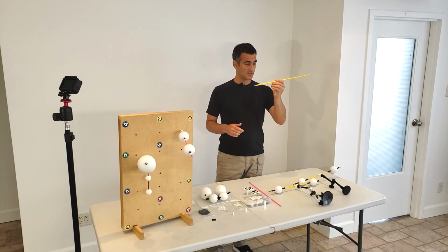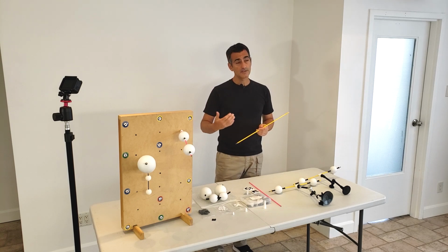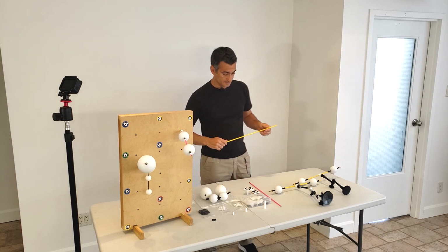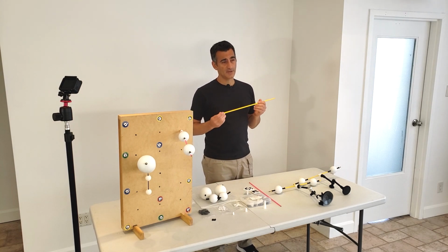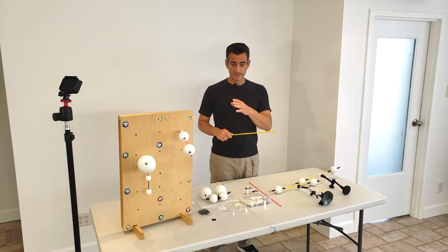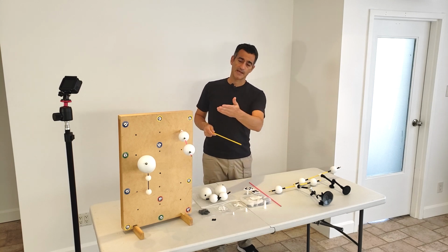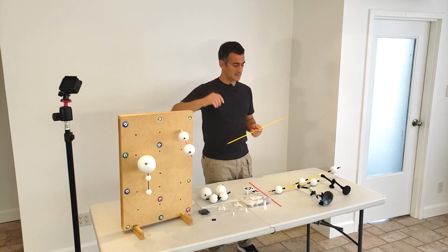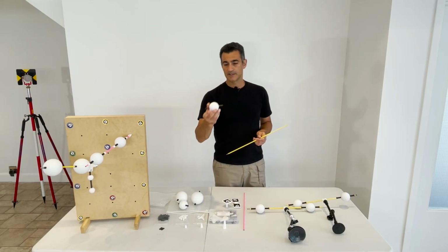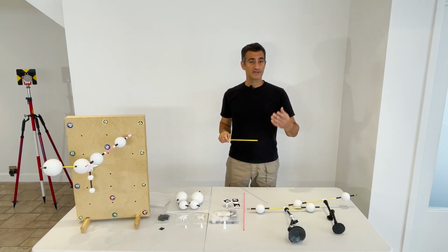You can use it with just a rod, taking photographs of the rod, or you can have certain types of targets, and that's what I have over here. One type of target that you can use on the rod would be spheres, and there are different types of spheres. I'll talk about them a little more on the laser scanning side, but I have two sizes here. The larger one is an 80 millimeter sphere, this one here, and the smaller one is the 55 millimeter sphere. Many programs now have sphere detection.